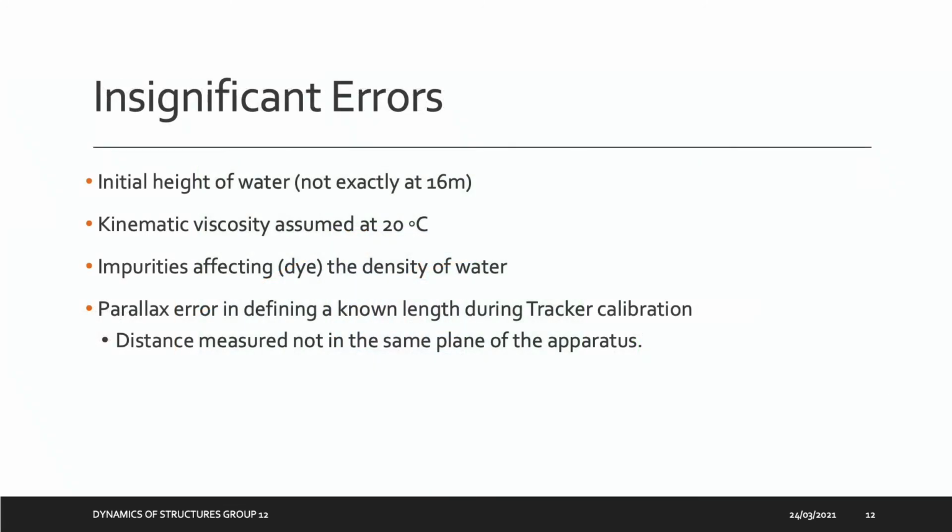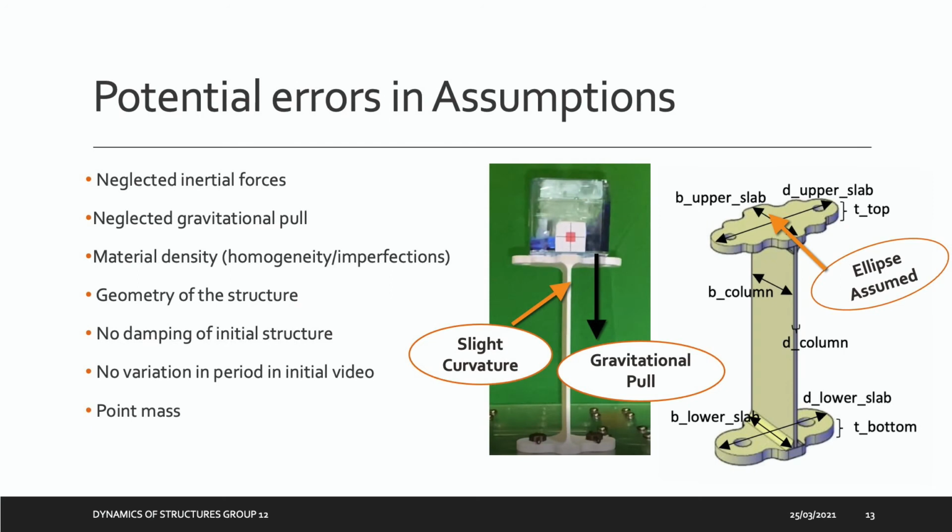Given that Tracker does not match the frames with the reference perfectly, these experimental errors are said to have minimal effects on the results. The difference between the estimations and observed displacements is implied by the uncertainty associated with the assumptions made. The severe underestimation of 0.5 mm is likely due to the uncertainty of the infill density, which directly affects the stiffness of the structure, causing incorrect UST predictions. Additionally, the model does not take into account the inertial forces exerted by the free-flowing water on the structure when there's a change in direction in the base motion.